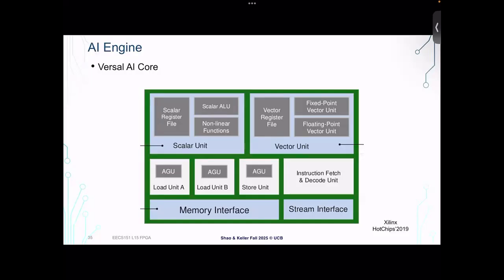There will be some part of it that's a field of programmable logic, made of CLBs. But then there are big chunks that are just these different specialized blocks that you can map onto, because they're trying to guess what people's most important workloads are and have specialized hardware to map onto those blocks. Okay, yes, question.